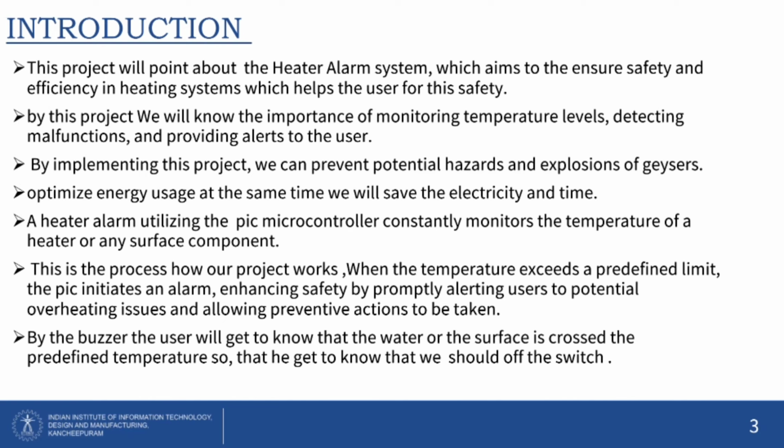This is how our project works. We set a predefined temperature, which we insert in the PIC microcontroller, and we connect an LM35 surface temperature sensor. When we bring a heat source near the LM35 sensor, if it observes the temperature exceeding the predefined temperature, it gives a signal to the PIC microcontroller, which initiates and rings the alarm, and simultaneously shows the temperature on the LCD display.